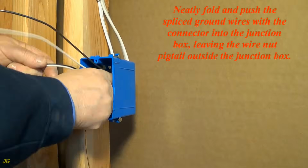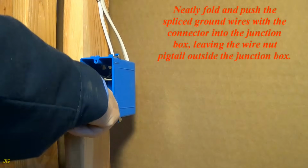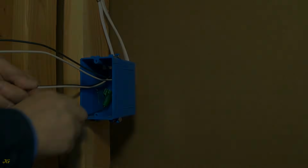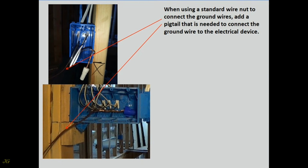Neatly fold and push the spliced ground wires with the connector into the junction box, leaving the pigtail outside the junction box. When using a standard wire nut to connect the ground wires, add a pigtail that is needed to connect the ground wire to the electrical device.